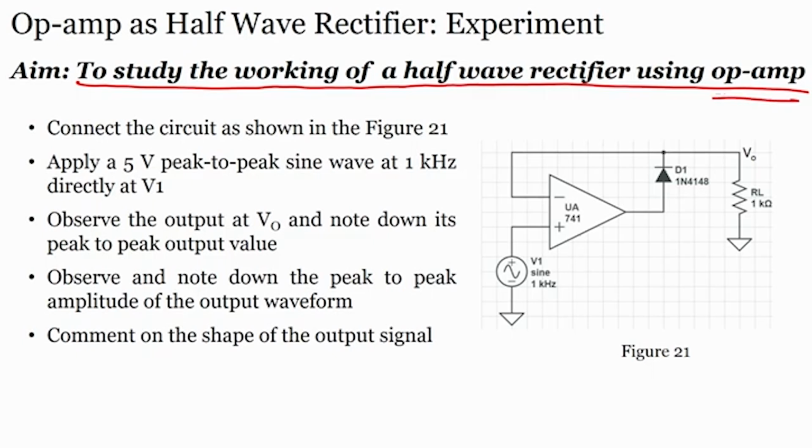Operational amplifier, we already know, performs various operations. We have already considered how this half wave rectifier works: when Vin is positive, this diode will be on; when Vin is negative, the diode will be off, and it will not pass. When the diode is on, this will be a voltage follower, as we have seen. What we have to do to implement this circuit, what we will apply as an input, and what kind of output we are measuring, let us see.